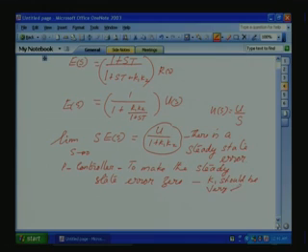See, this may not be feasible in many applications. For K1, there is always a controller amplitude limit. K1 we cannot have any value. So, with the proportional controller there is always a steady state error.